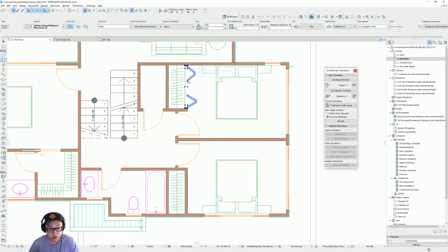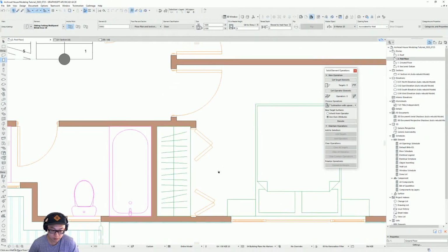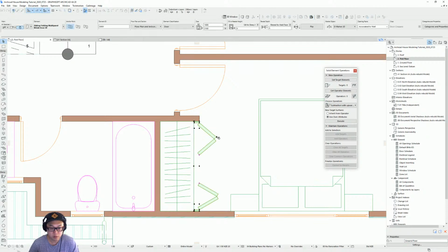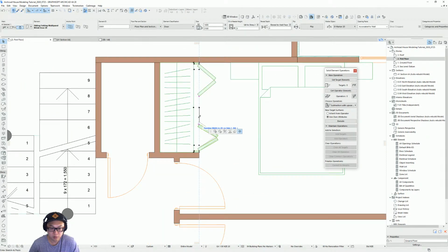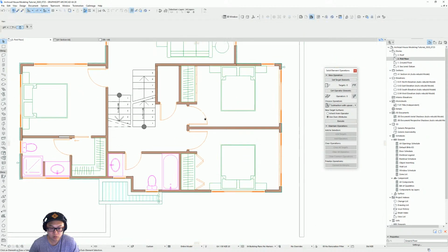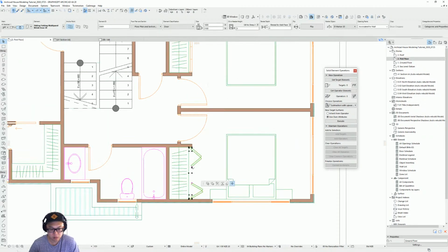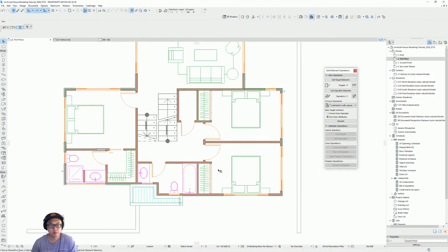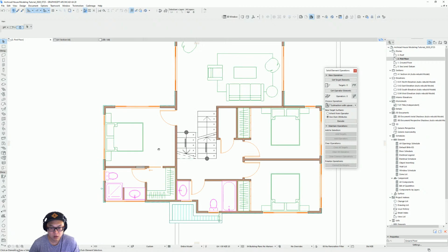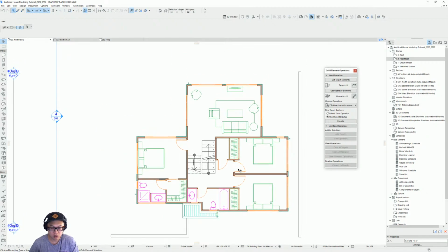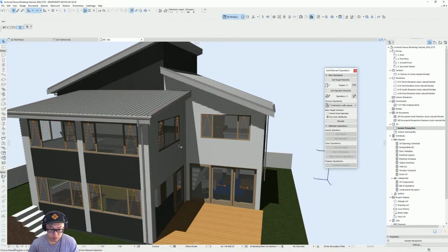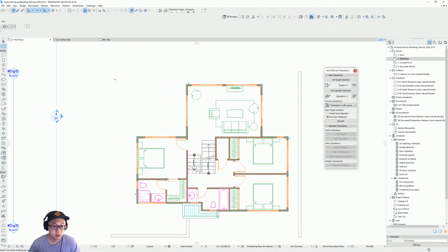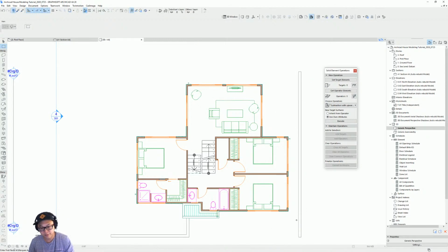And now I'm just going to absorb the properties of this and click on the other walls. Move it into place. And graphically, if you wanted to, you could select some of the points here and close it, just to make the room a bit bigger visually. And I think here we also need to move some of those 900 down. So in here, you can see those are floating. So what I'm going to do is select all of this and press F5.